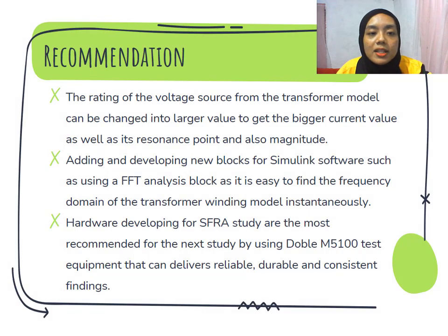For the recommendation, firstly, the rating of the voltage source of the transformer model can be changed to a larger value to get a bigger current value as well as its resonance point and magnitude. Secondly, by adding and developing a new block for Simulink software, such as a fast Fourier transform analysis block, it is easy to find the frequency domain of the transformer winding model instantaneously.